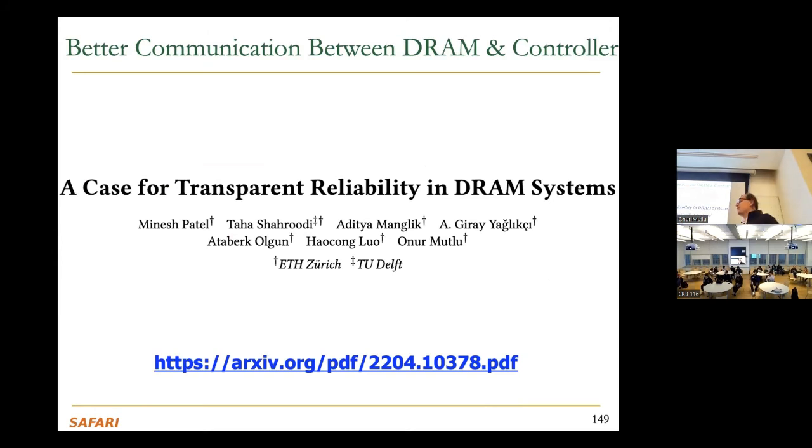Yeah. So for example, if you find the bit flip online during online operation, there's a mechanism called page offlining. You could offline that row, offline that page. And this is used when people find memory errors in the field, for example. It's used in data centers like Facebook, Amazon, etc. That's one mechanism. It's a heavyweight mechanism, but you could use it today.